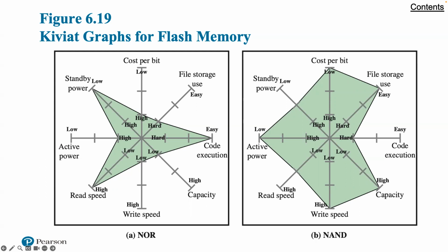NOR flash memory provides high-speed random access. It can read and write data to specific locations and can reference and retrieve a single byte. NAND reads and writes in small blocks. NAND provides higher bit density than NOR and greater write speeds. NAND flash does not provide a random access external address bus, so the data must be read on a blockwise basis, also known as page access, where each block holds hundreds to thousands of bits.